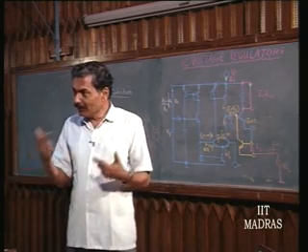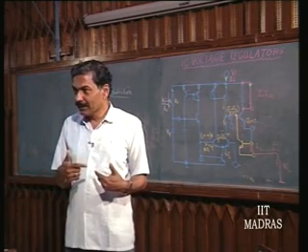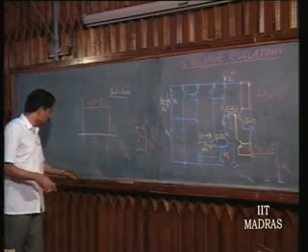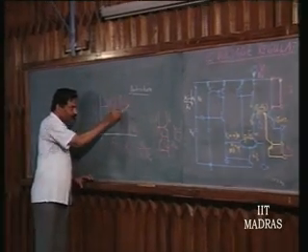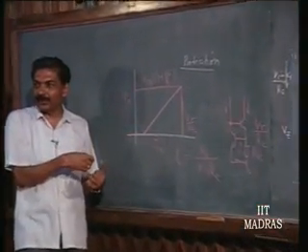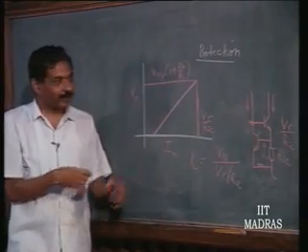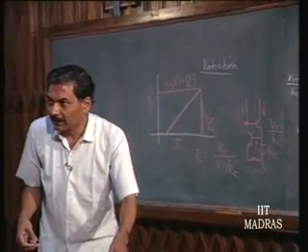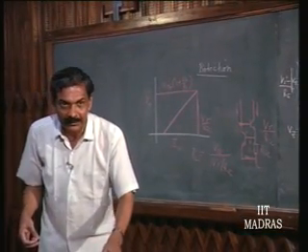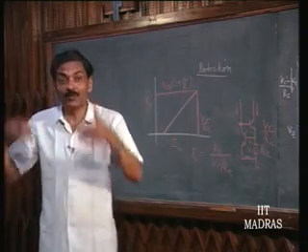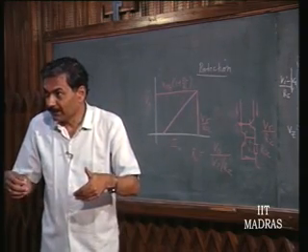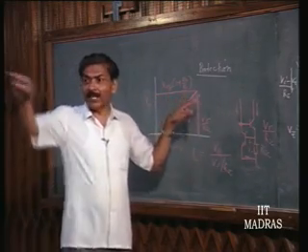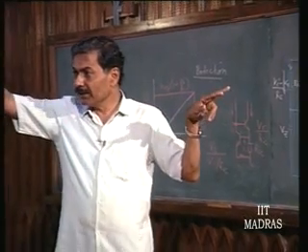So, depending upon what V naught is likely to be, I would like to therefore convert it into something which is not at all a current source. This is Foldback short circuit protection, because after this load resistance is connected, for all the lower values of load resistances, it need not be a constant current. That means I have to sense the output voltage also, apart from output current. If the output voltage becomes different from this, then I need not sustain that constant current through the resistor.